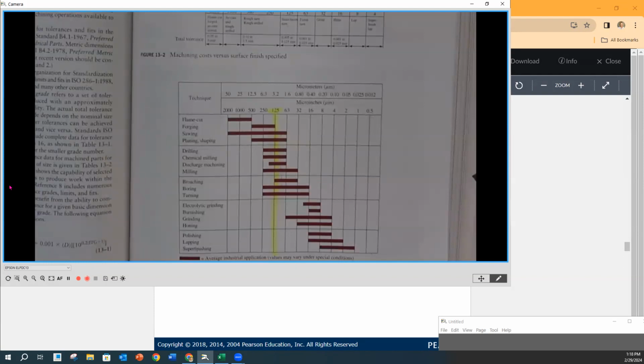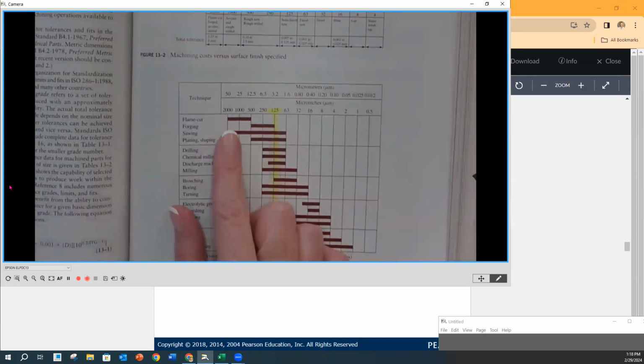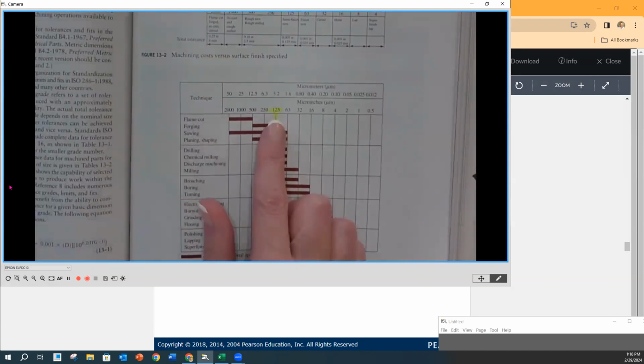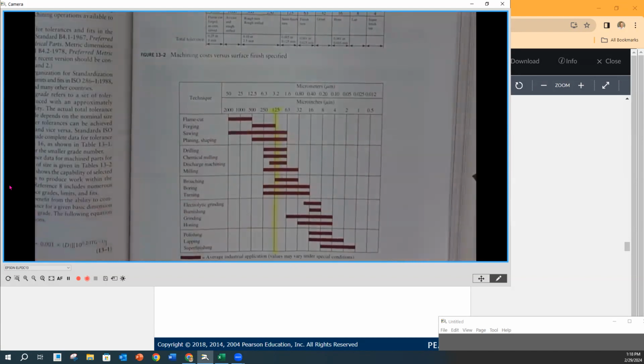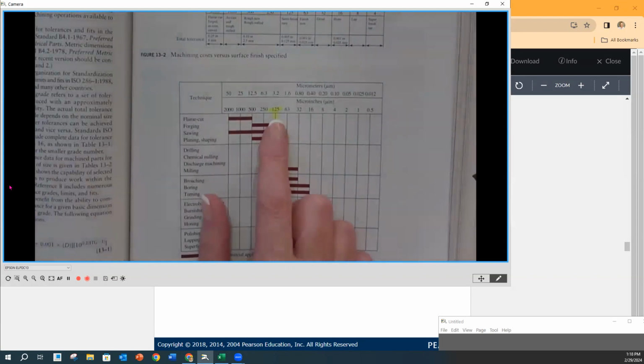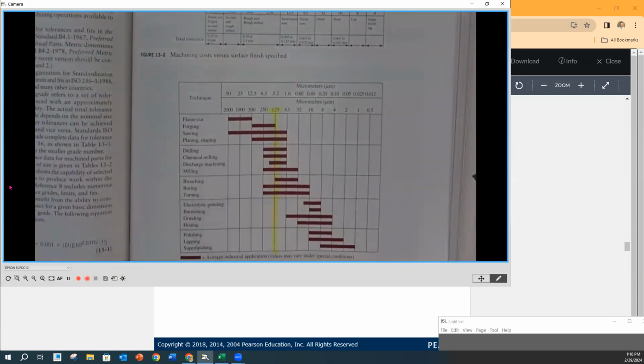That's another case where if the tolerance is loose, like down here on the manufacturing processes side of things, but you want a nicer finish, not crazy, but you want it to be a finished finish, then you would want to add a 125. Does that make sense? Yeah.